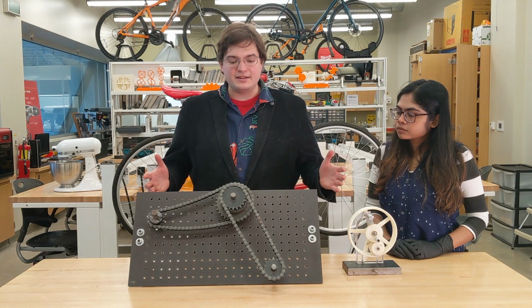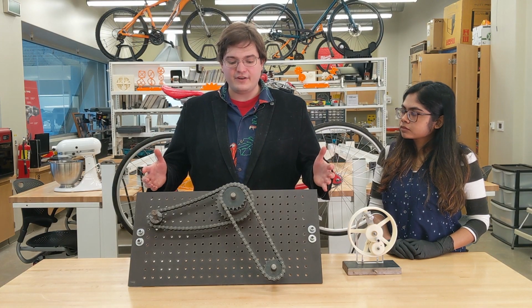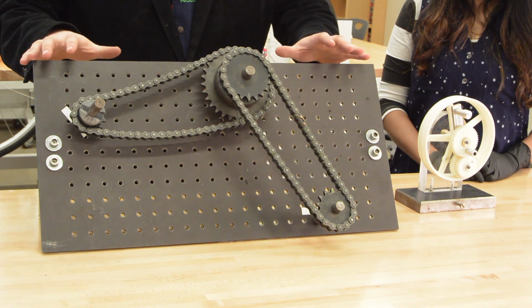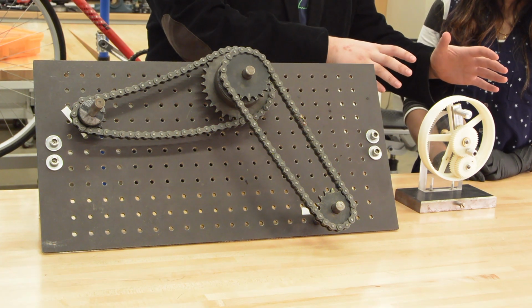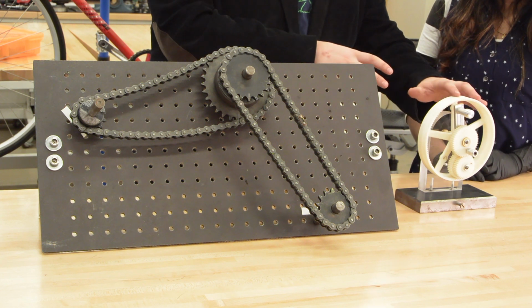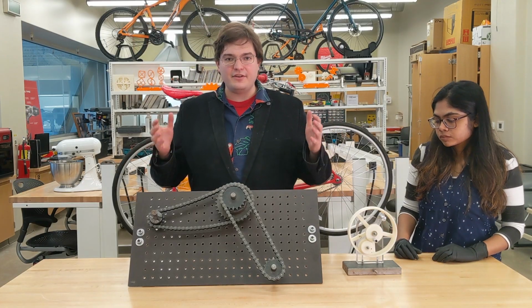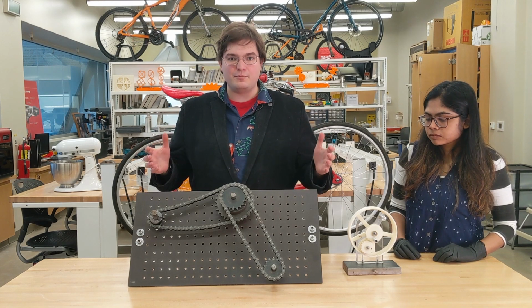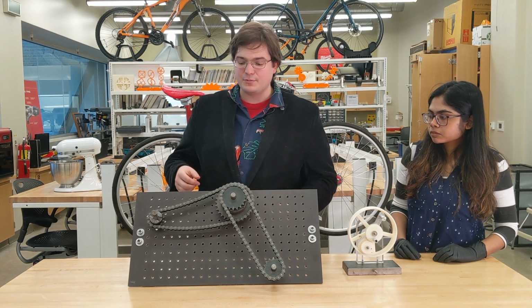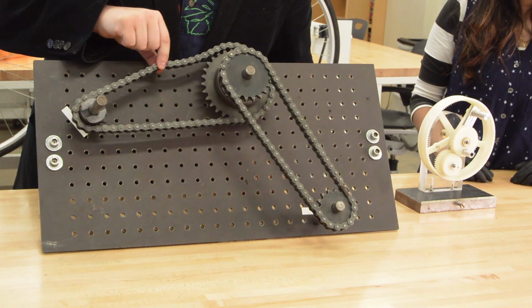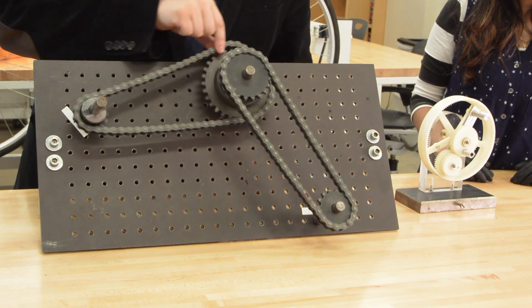To demonstrate this, I've provided a set of 2 devices to look at. A 1 degree of freedom system here, this sprocket set, and a 2 degree of freedom system set over here with these planetary gears. Degrees of freedom are the number of inputs required to fix an output in a system. So on this sprocket set, you can see that I'm putting in an input, and I get out a single output.